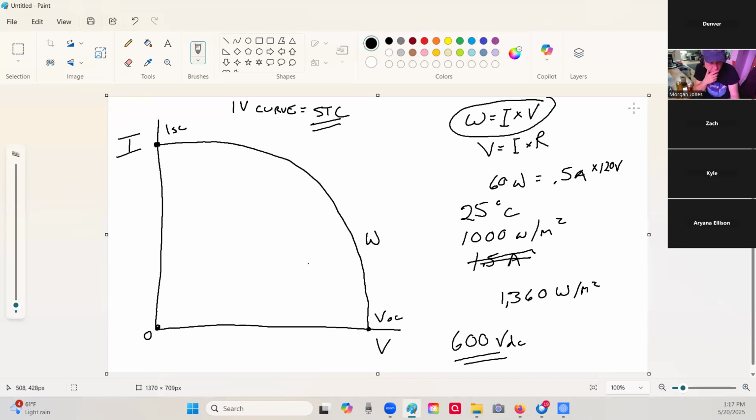So those two numbers I use when I'm designing my system because they're theoretically the biggest numbers that panel might produce. Now you'll find later that we've got to adjust it for temperature, but at the moment, just conceptually, just understand you're dealing with those numbers for design.